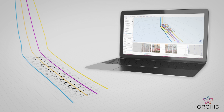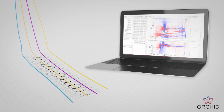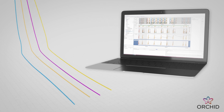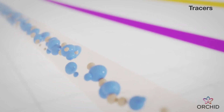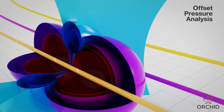Understanding the fracture distribution created downhole demands the right metrology. One relatively easy way to understand interactions between wells is to record pressure and temperature time series whilst fracturing. When water and sand are injected into a treatment well, the stress field that is generated can be recorded on a nearby well by downhole or surface gauges.